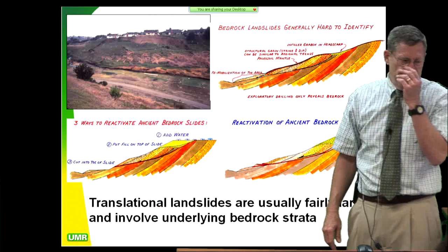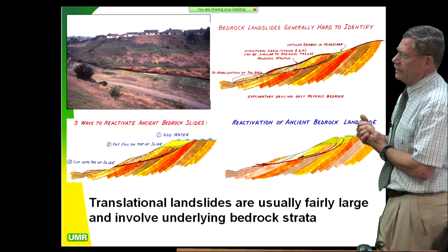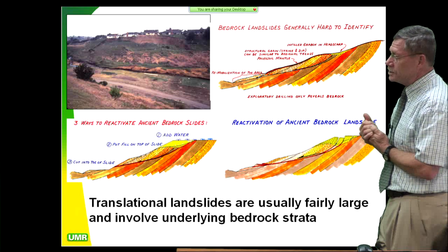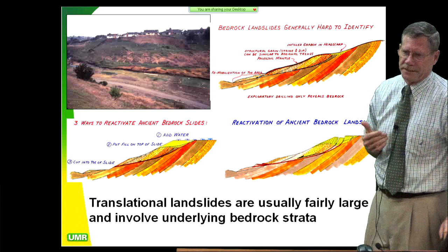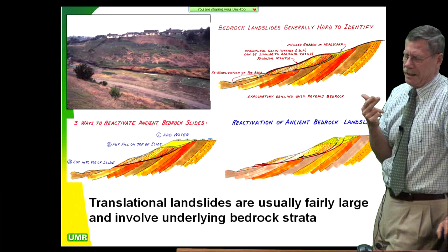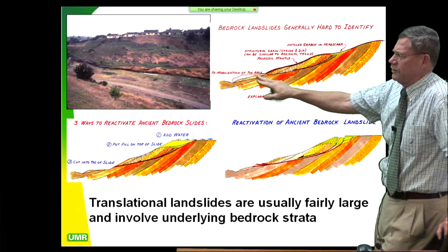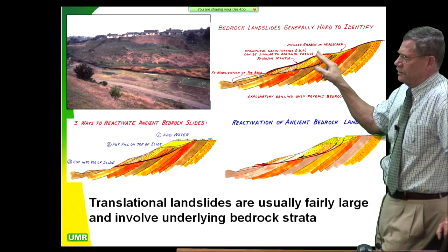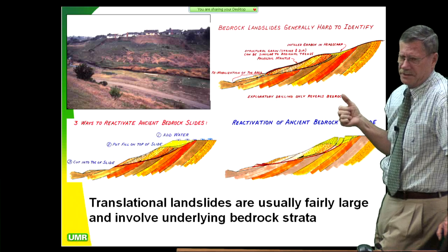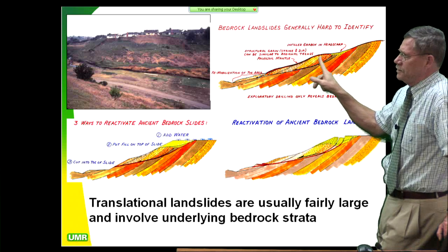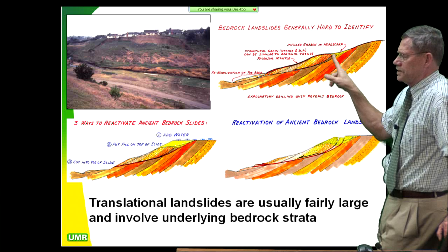Now, bedrock slides are always problematic because of the way engineers are trained. Most geotechnical engineers are trained to go out and look at a site and give foundation recommendations. So the focus of their training is on looking at shear strength and bearing capacity. So you come out to a site like this, a pretty typical California site, and you drill the site and you've got weathered bedrock. And the weathered bedrock has pretty good blow counts using the standard penetration test. So you tell them 2,000 pounds per square foot allowable bearing, and you're off to the races.